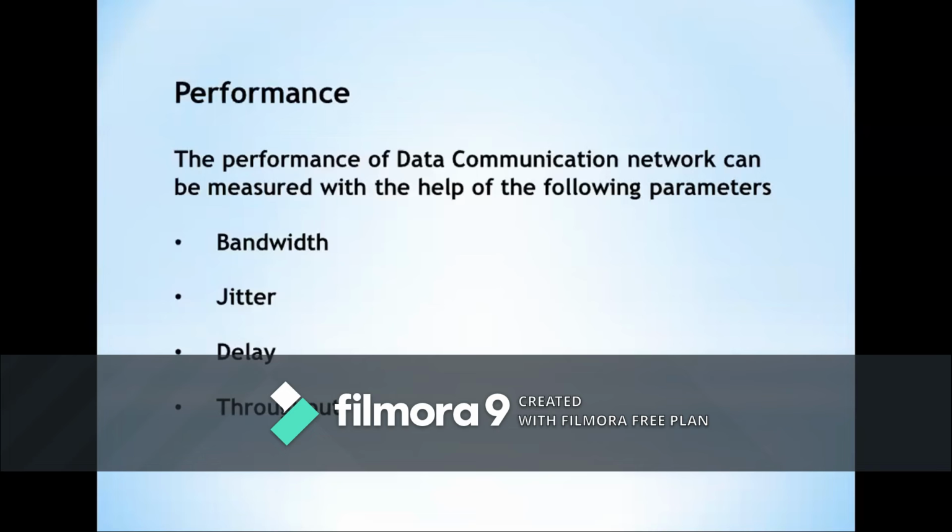The maximum rate at which pulses can be transmitted through the channel is given by: maximum rate is equal to 2W pulses per second, where W is equal to 1 by 2 Tau, and Tau is the smallest pulse width of the input signal.